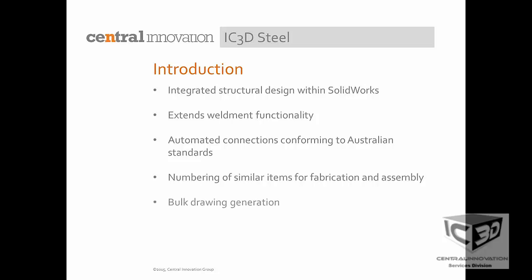Just speaking of creating drawings, we have bulk drawing generation. So all of the items that you want to create a drawing of in your structural steel design, all of the drawings can be created at once. So you'll have, could be dozens, could be hundreds of drawings. They'll all be created for you, and then it's about time to going back and detailing them. So a great sort of time saver there as well.